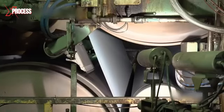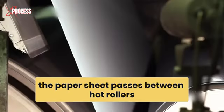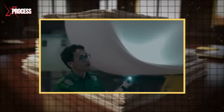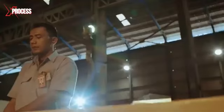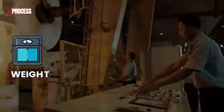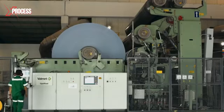Subsequently, it passes through a calendaring stage, where the paper sheet passes between hot rollers that smooth and improve the uniformity of the paper's surface. Next, technicians check the paper's quality parameters and note any anomalies. Throughout the process, quality controls are performed to ensure the paper meets the desired standards. The weight, strength, and smoothness are inspected. Then, the paper is rolled.